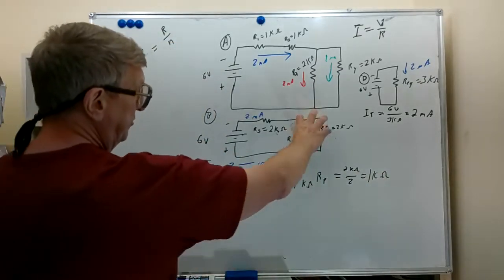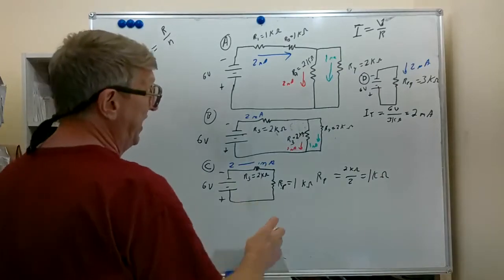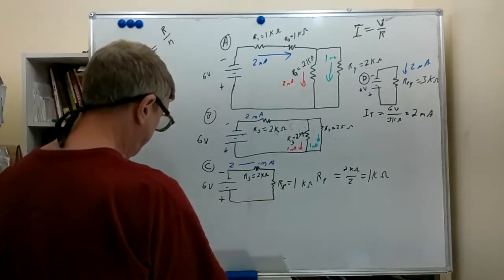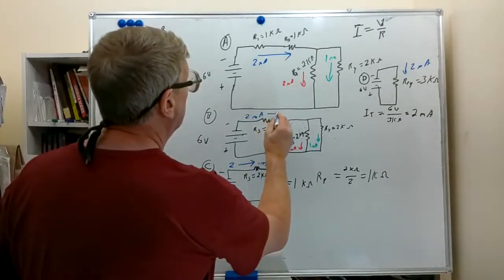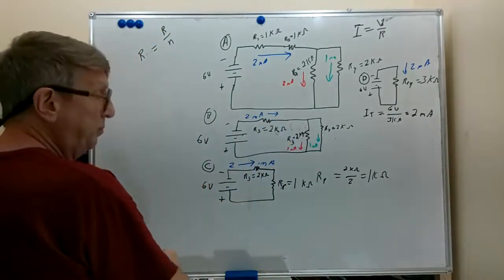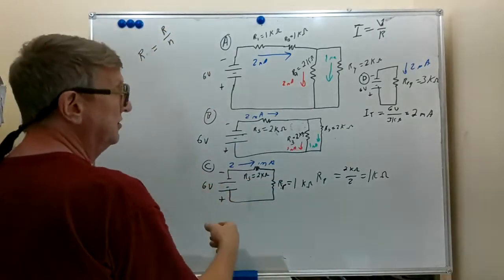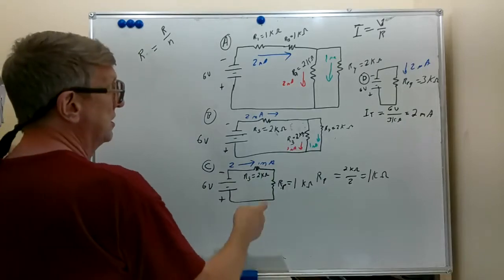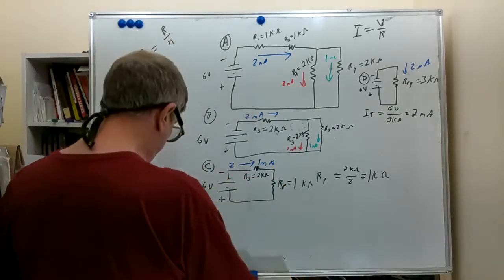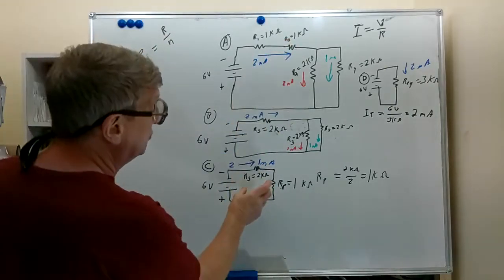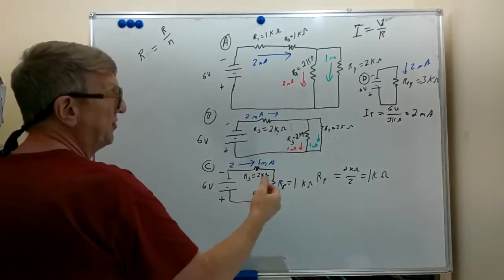So replace this parallel network, or parallel bank of resistors, if you like to call it that, with a single resistor, we call it RP, equivalent resistance for the parallel network. Now to simplify a little bit more, we added the R series that we got from combining these of 2 k ohm and the R parallel that we got from combining these to get 3 k ohm.